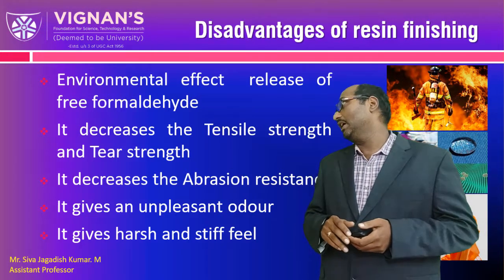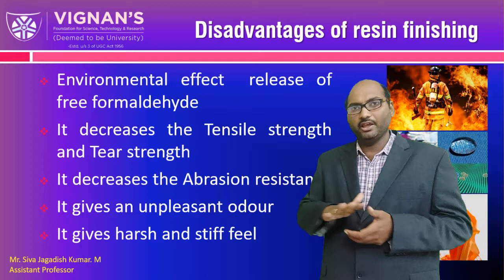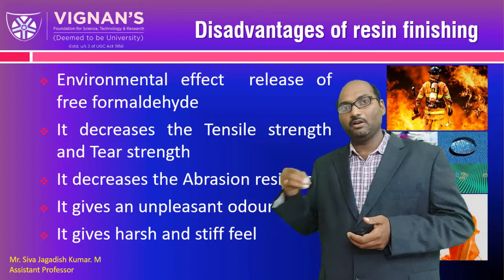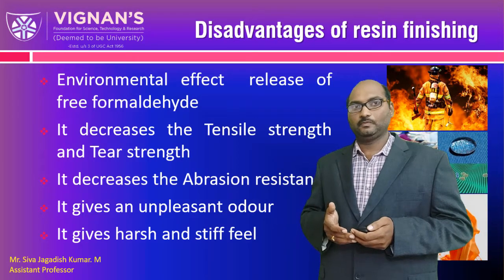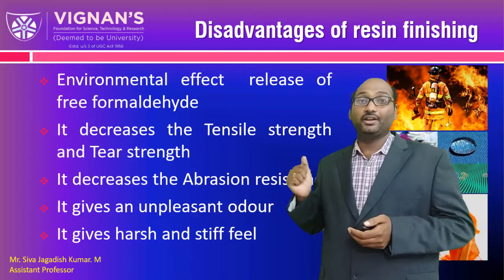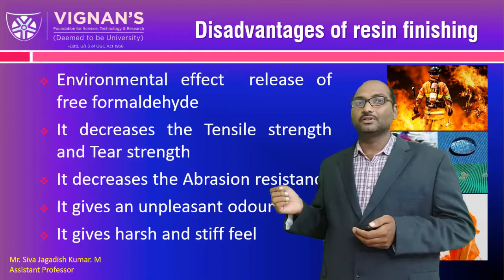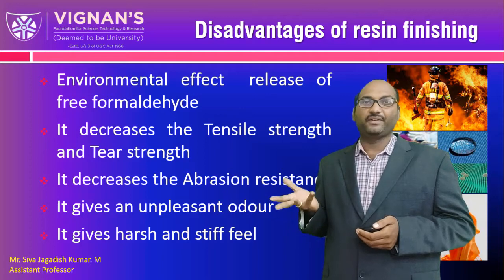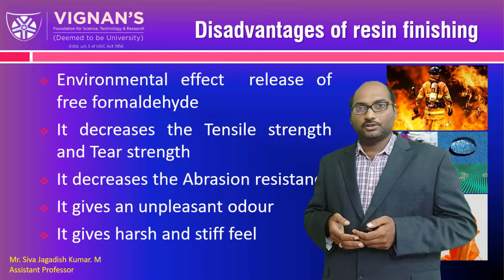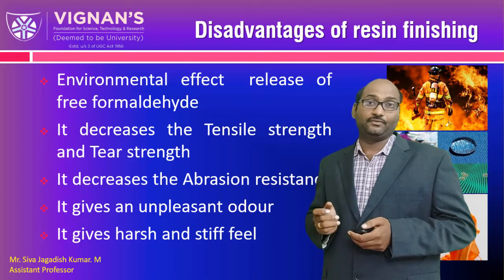And also it decreases the abrasion resistance. It forms a layer, yes, of course. So initially it will provide a very strong layer, but once it peels off, it will easily come out. Okay. And the next one is odor. It gives bad smell. And the feel and all, if you consider, it gives harsh feel and stiffer feel. Obviously we understood it. It becomes more stiff and weighted. Okay, stiffness and hardness also will be improved by means of this resin finish.